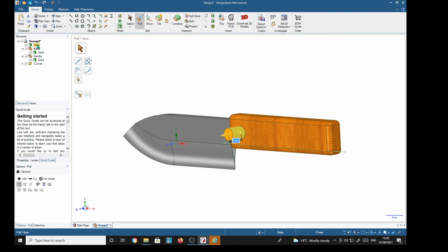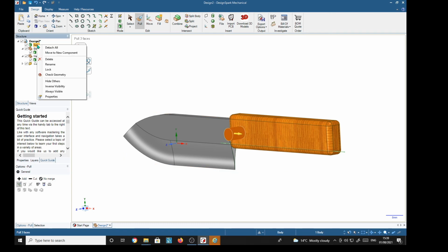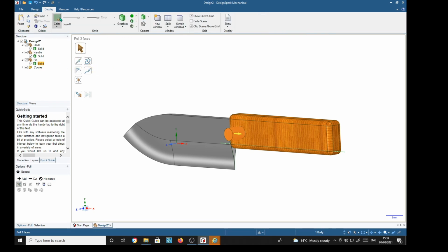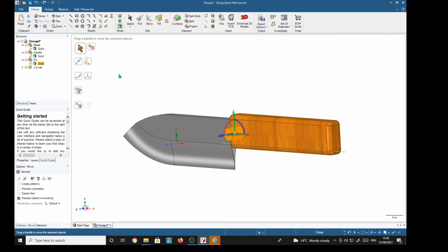and that is an extra solid here. So I'm going to make that into a new component also. There, and make that pin. Select the pin, solid, display, color, yellow, so it will stand out. Back to design, move. Click somewhere and you see it's nice yellow color. Pin,